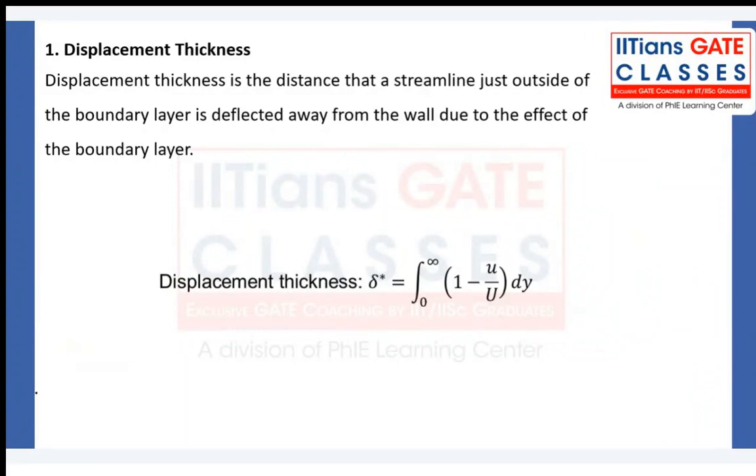Here, basically, you try to remember it is viscosity which is happening because of the momentum exchange, right? A lot of momentum exchange is happening in the turbulent flow. Momentum exchange doesn't mean only from a higher fluid layer to the lower fluid layer. It can happen from the lower fluid layer to the higher fluid layer also. And below any fluid layer, we have fluid layers which are badly slowed down by the effect of the wall.